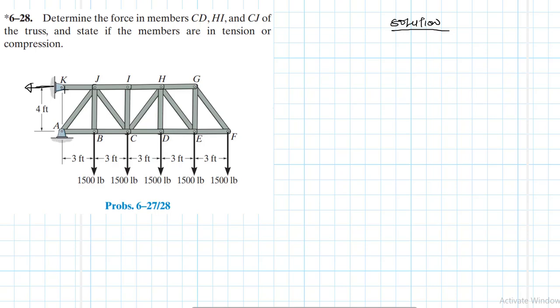Because we only have one member connected at this joint, and for trusses, the force is always along the longitudinal length of a truss, because truss members that are usually used are always straight. So you expect the force in KJ to be along the length from J to K, and therefore the reaction at joint K will just be in the same direction but opposite. So at K, you're only going to have one support reaction, even when it is a hinge, okay?